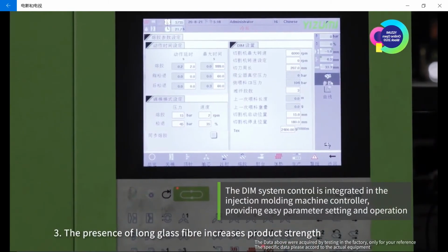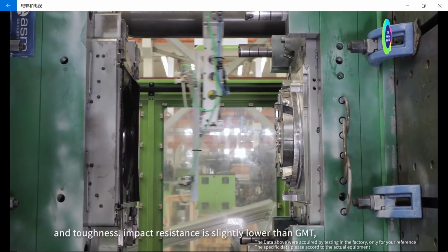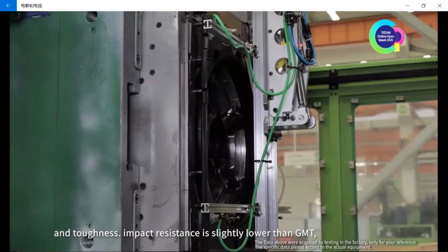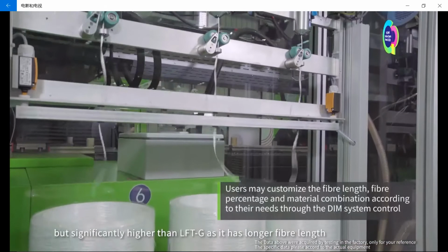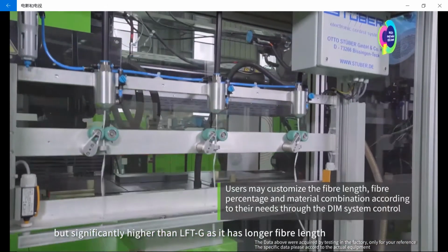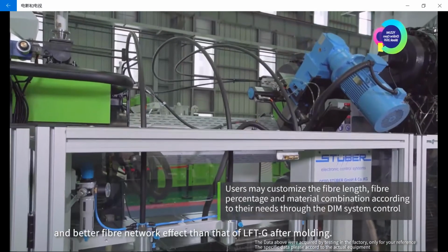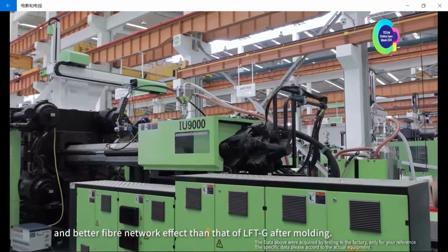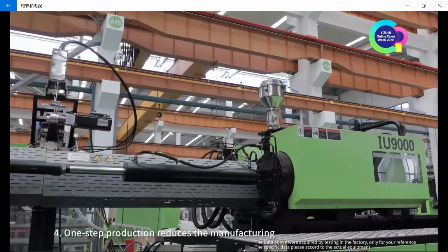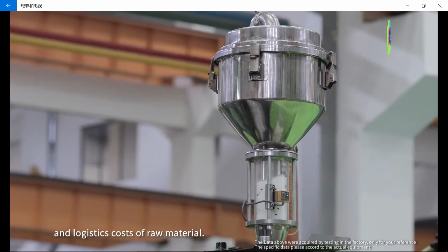The presence of long glass fiber increases product strength and toughness. Impact resistance is slightly lower than GMT, but significantly higher than LFTG, as it has longer fiber length and better fiber network effect than that of LFTG after molding. One-step production reduces the manufacturing and logistic costs of raw material.